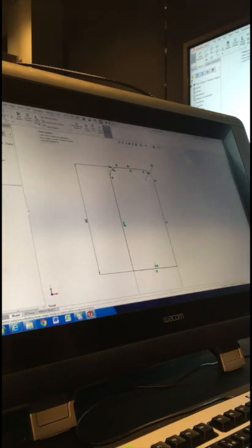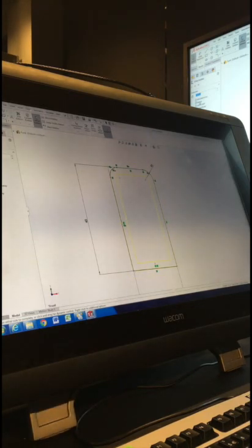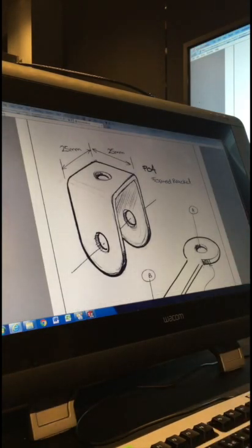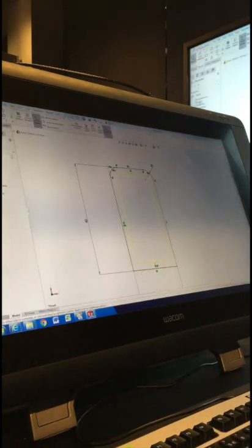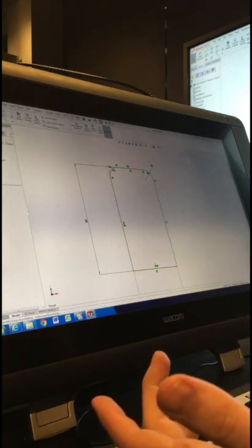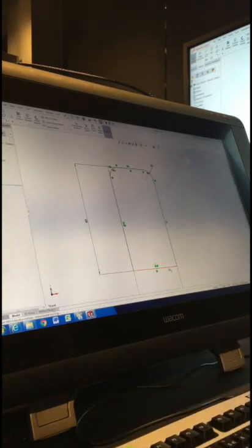With this offset entities, I'm just going to uncheck some of those settings there. Let's change that thickness to 3. Let's select that line at the top and select reverse. See how it's offsetting that bottom line as well, okay, in the preview, but in this shape it goes straight down to the bottom. So we don't want to include that bottom edge. So I'm going to just press escape to cancel that offset. I'm going to select that bottom line and make it for construction.